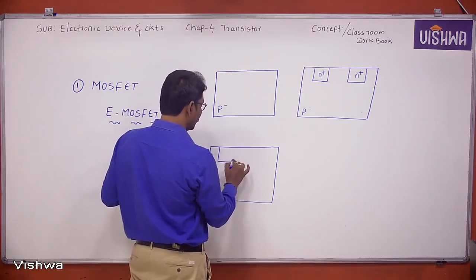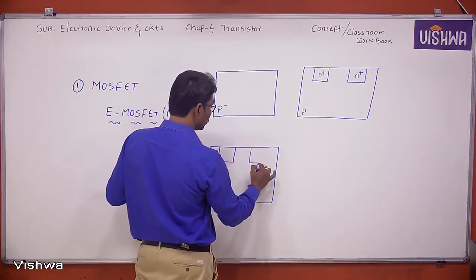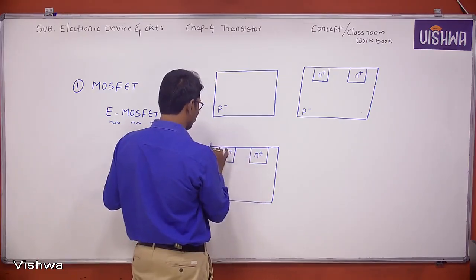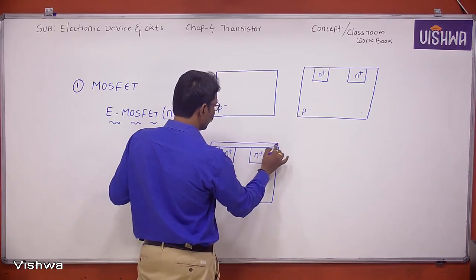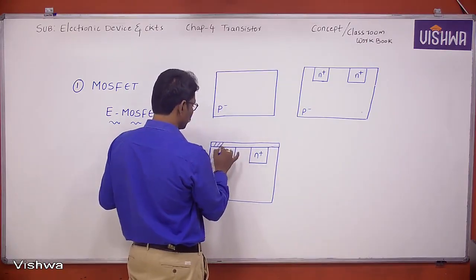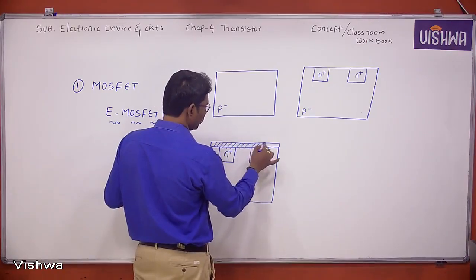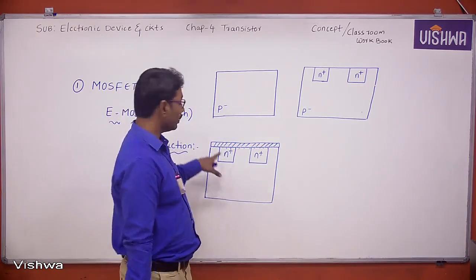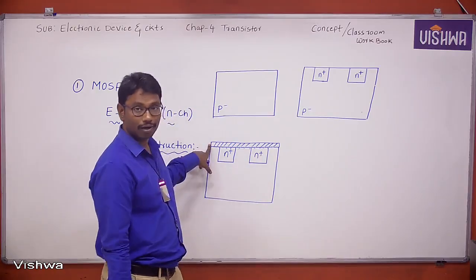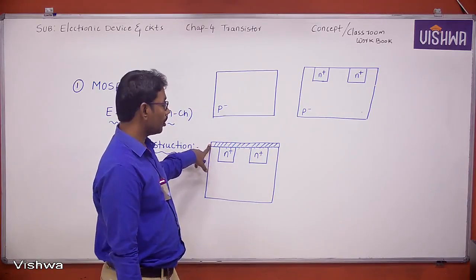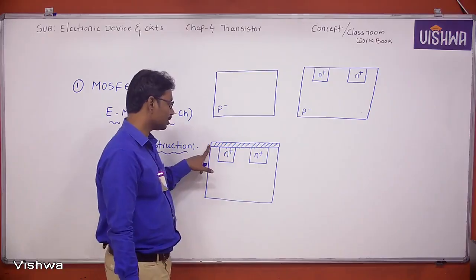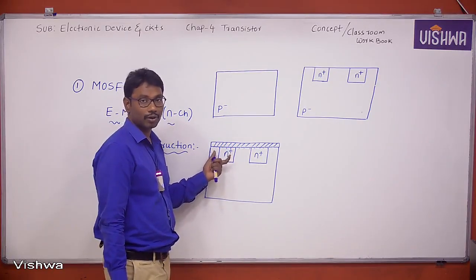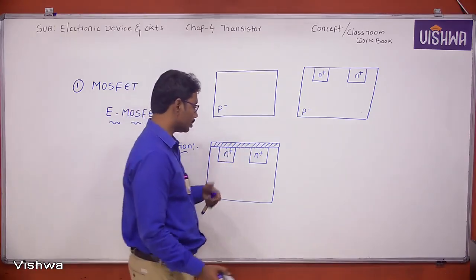And step 3 is, see, an oxide layer is formed over the substrate. By using what process? Oxidation process. Then it can act as an insulator or dielectric or masking. And what is masking here? Masking is nothing but selective portion of doping. Selective portion of doping is called masking. This is our step 3.